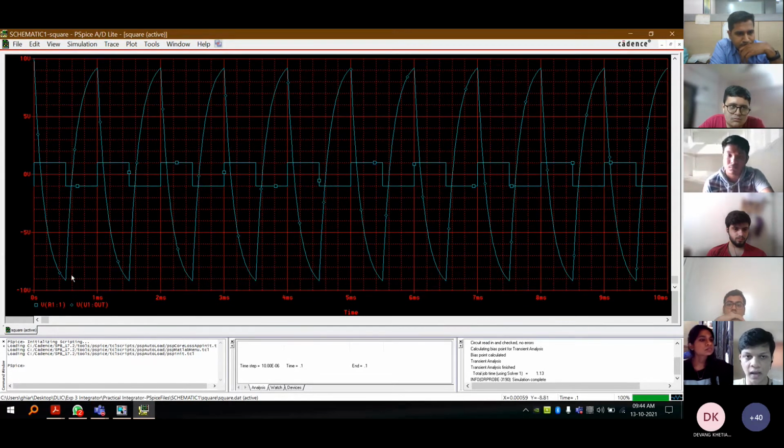And you can see that we have a sawtooth wave generation. So what we actually want is a triangular wave generation. But what we are seeing here is a sawtooth wave generation. Basically, it's a triangle, but it's not perfect. It's the exponential rise and fall that Mayur sir spoke about earlier. And as and when we change the frequencies, we will get a more sort of triangular wave.